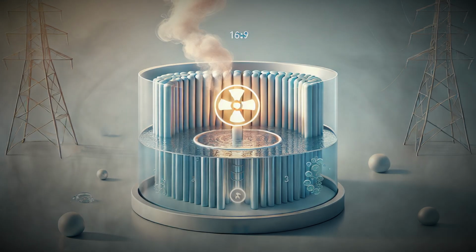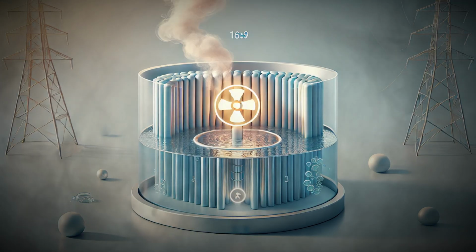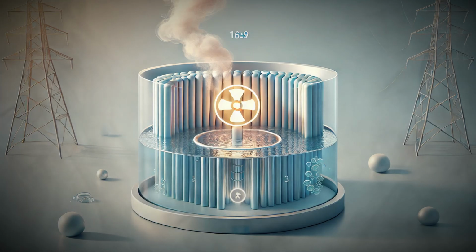When discussing how a nuclear power plant works, it is important to understand how the process of nuclear fission is transformed into usable heat, because the entire purpose of the reactor is to convert the energy released from splitting atoms into thermal energy that can then be used for generating electricity. Each time a uranium-235 nucleus undergoes fission, two main forms of energy are released.